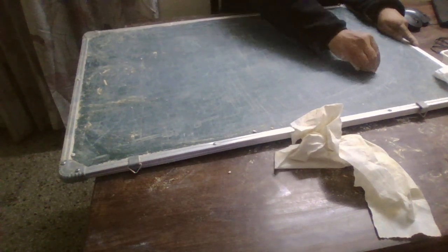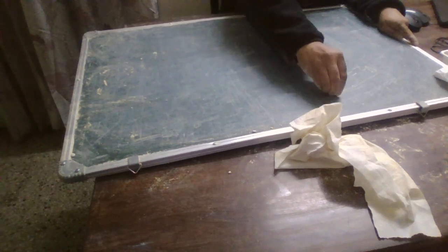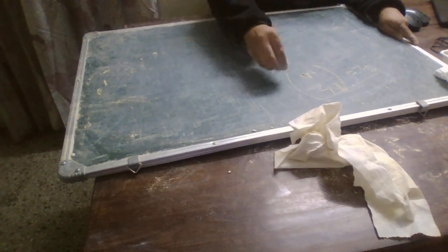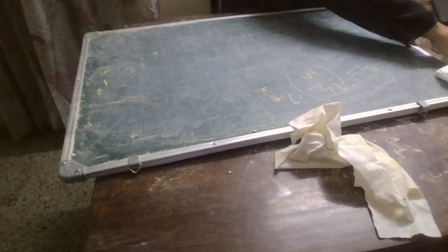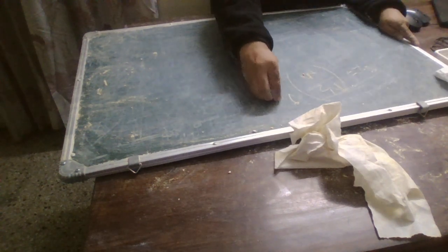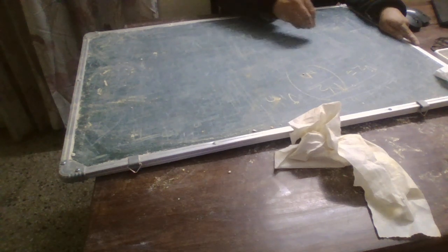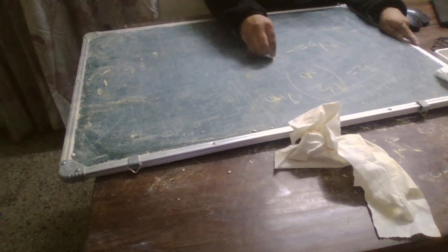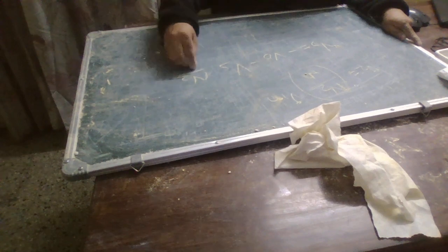So this was the primary side. Now on the secondary side, or the load side, V2 would be N2 upon N1, the number of turns, into V input. So we are going to have Vd equal to minus V0 minus Vs into N2 upon N1.